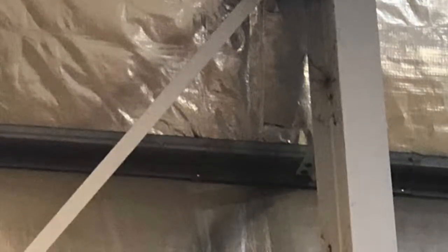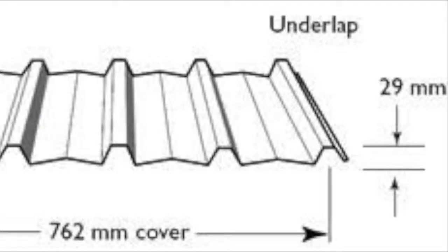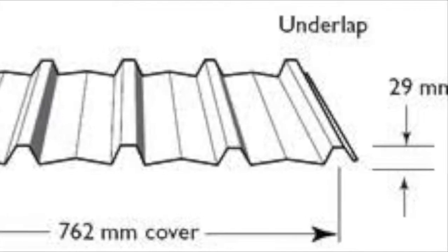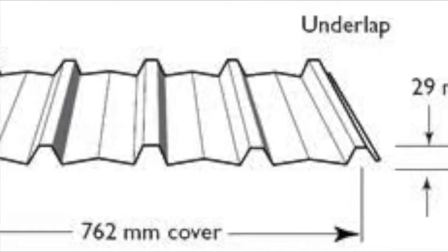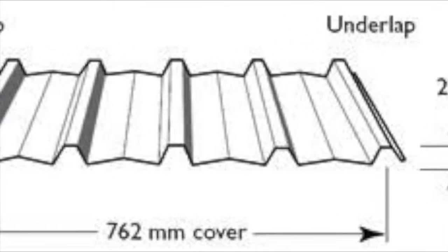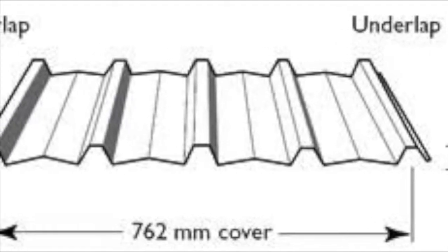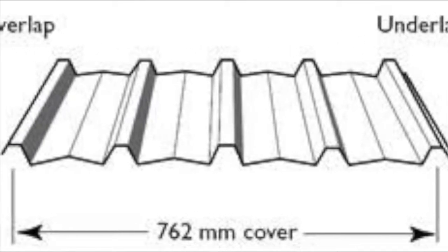Following the bracing, roofing is fixed to the purlins, and in most cases the typical roof sheeting used is Lysaght Trimdek. This is because the sheets are lightweight and provide increased wind resistance when compared to other roofing materials. Supporting the sheeting on the walls of the structure is a girt. Along with wall bracing, these girts give lateral support to the wall panel to aid in reducing wind loads.